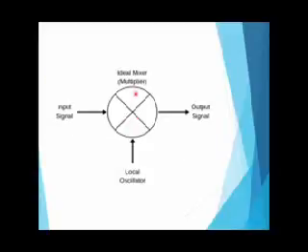Heterodyne processing translates the incoming TV signal to a different frequency. The cable companies use modules called heterodyne processors to translate the received signals to the desired channel. All signals on their final channel assignment are sent to a combiner, which is a large special purpose linear mixer.